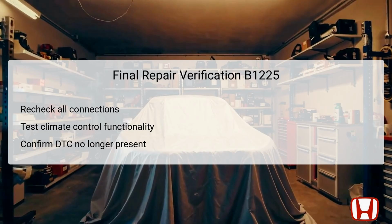This should include checking the in-car temperature readings and ensuring that the HVAC system responds correctly to temperature adjustments. Lastly, utilize the Honda Diagnostics system to confirm that DTC B1225 is no longer present in the system. By carefully performing this final check, you can ensure that the repairs made were effective, allowing the vehicle's climate management systems to function properly once again.